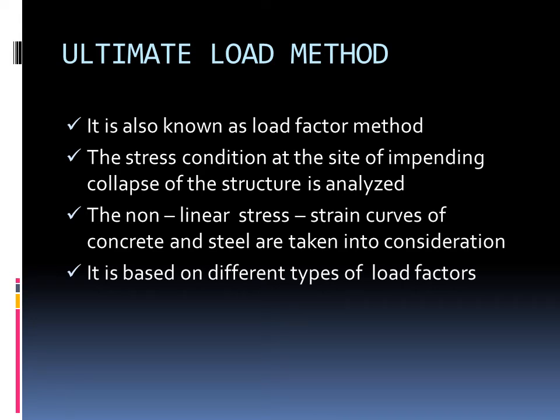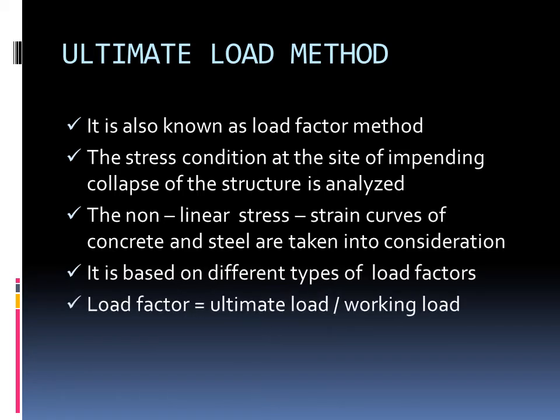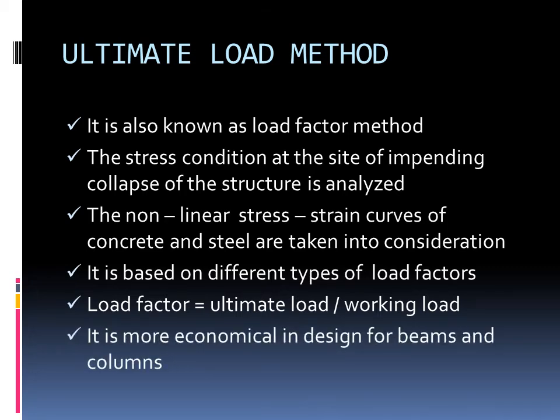In working stress method, we use factor of safety. In ultimate load method, we use load factor. Here, load factor is defined as ultimate load by working load. It is more economical in design for beams and columns.